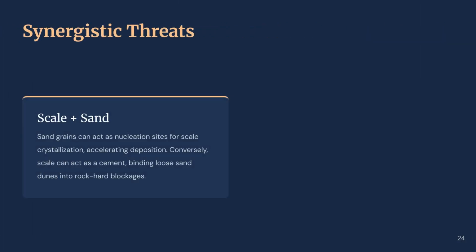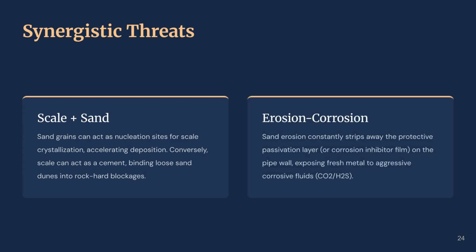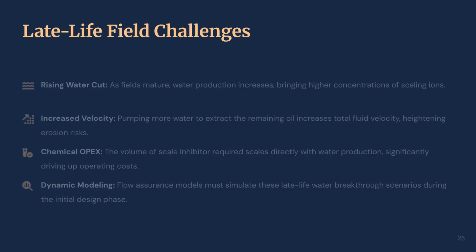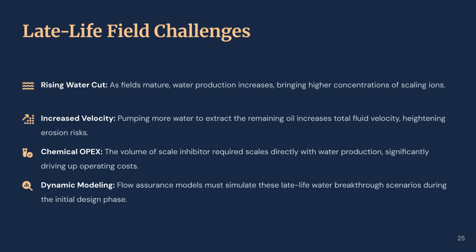We must also consider synergistic threats. Sand can act as nucleation sites for scale, while scale can cement sand into hard blockages. Furthermore, erosion strips away protective corrosion layers, exposing metal to aggressive corrosive fluids. Late-life field operations introduce unique challenges. Rising water cuts increase scaling ions and fluid velocity, while also raising chemical operating costs. Engineers must use dynamic modeling to simulate these conditions early in the design phase.